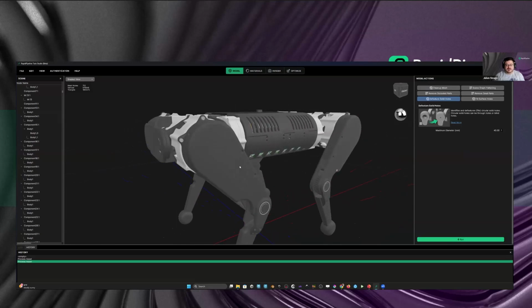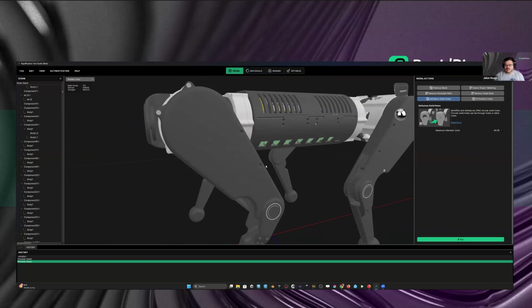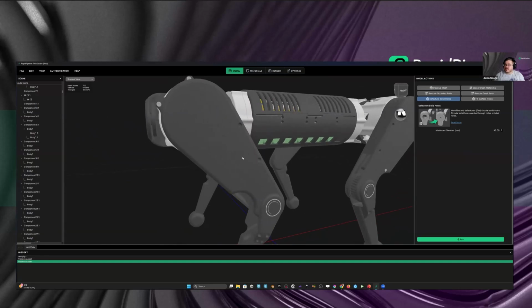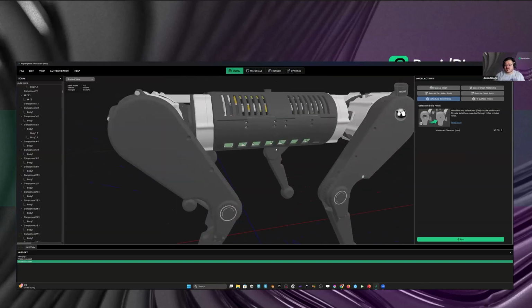And yeah, this is basically one of our first defeaturing settings, and there will be more to come. So also looking at other shapes of holes, of course. But as you can see, this is not just a simple surface hole on one side of the mesh with broken topology where we fill that gap in, but it actually closes the geometry and leaves no trace behind, let's say, in that regard.